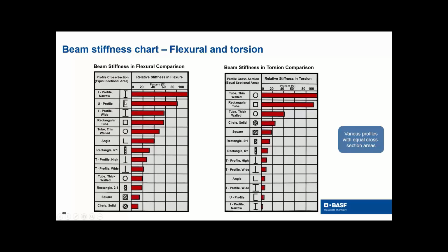And then it goes down a little bit. There's a U profile, or I'll call it a C profile, a wider I-beam, and then, interestingly enough, some hollow sections look pretty good. So knowing that, okay, good. But if your application is only going to see torsion, what do the cross sections look like? Well, it's saying the hollow sections work the best.